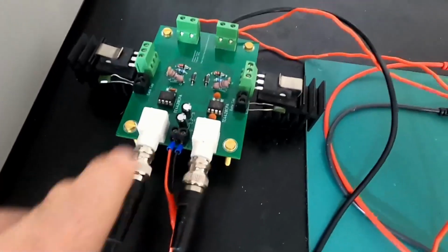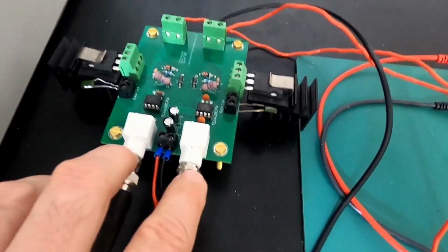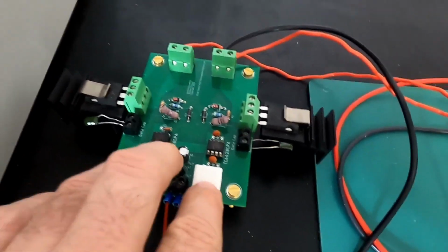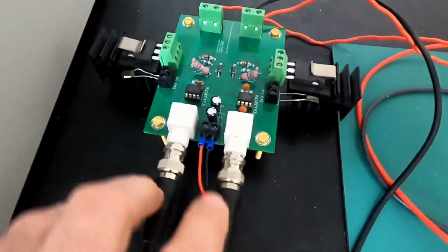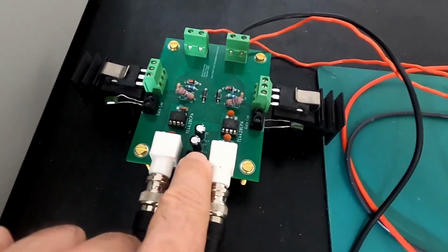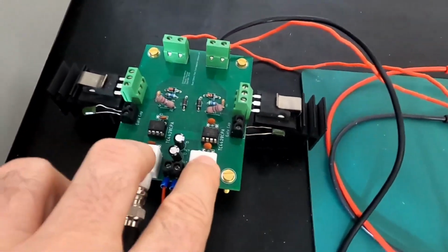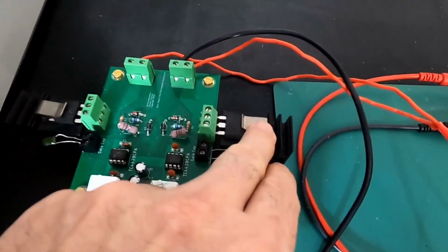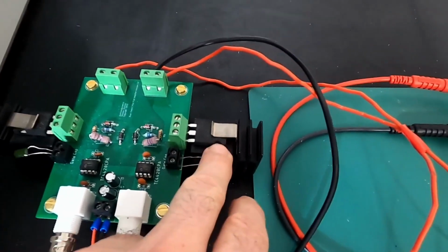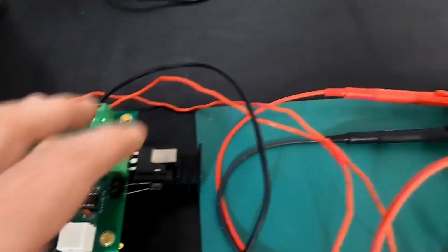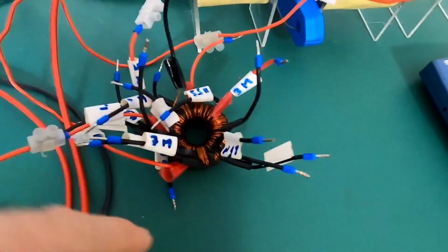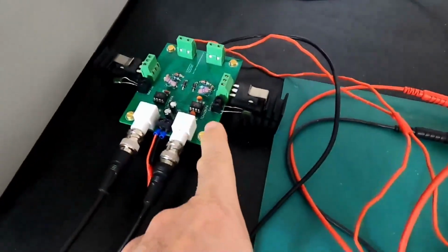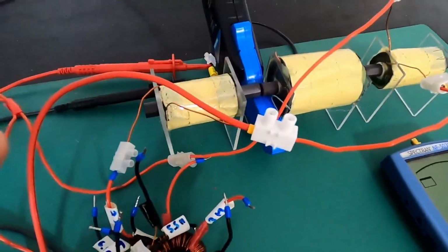Before I used a coil with center tap. That is not required anymore. By using 2 chips, with inverted and non-inverted, it works just fine. I probably will build a new board where I have only 1 BNC connector in there. That would save components. Only 1 signal coming in is good enough. So we have currently only these 2 MOSFETs, the IRFP140, and we go out in a normal way. And you see again my impedance transformer, because here I have very, very low impedance, and here I have high impedance, so it's the other way around.